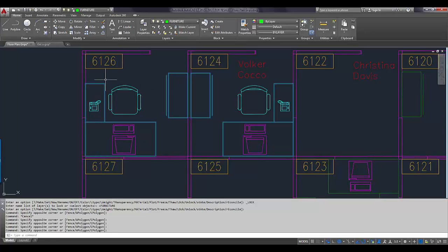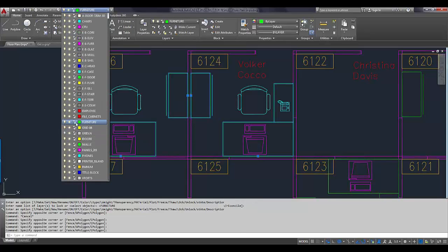Anyway, when you lock a layer, those grips don't appear. So if you know for sure your grips are enabled in options, but they're not appearing on the drawing, maybe it's because that layer is locked. That's one of the first things I would check in that case. The locked layer will also fade out, but some people do turn that off.